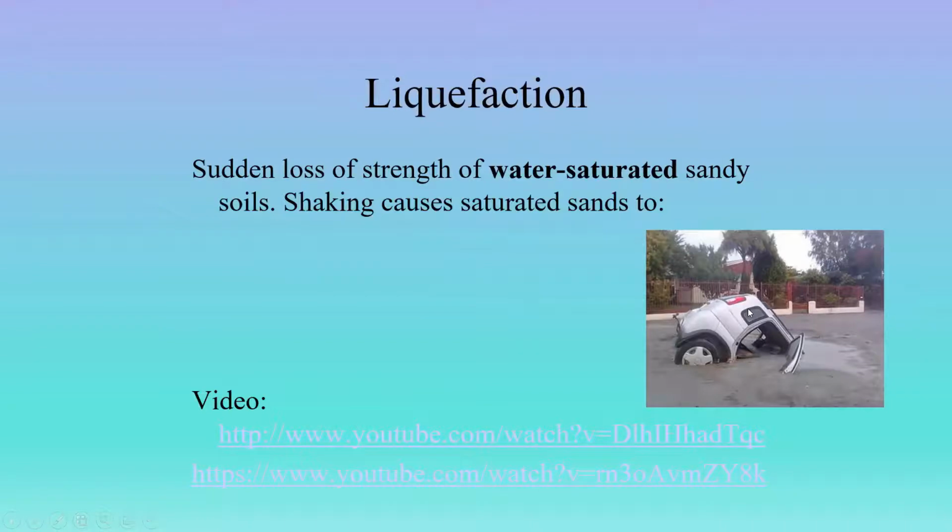But basically, what happens is during an earthquake, as you get the shaking, it starts to push water up into these soft soils and sediments, right? And that causes these sands to be saturated and then partially supported by water, which really is no support at all.